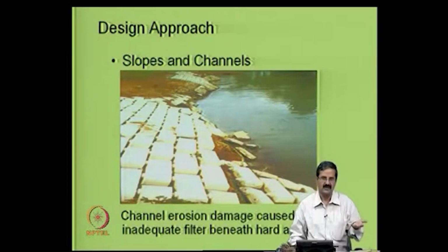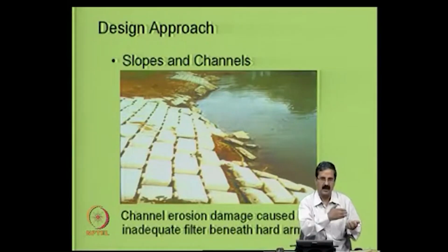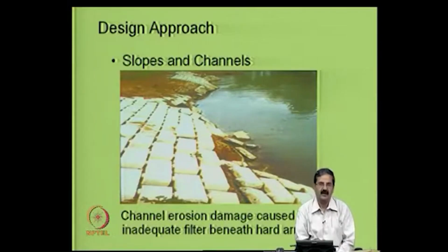The soil is under saturated conditions now, and the effective stress is very low. The water tries to come out, and when it tries to come out, the possibility is that the retaining wall can fail. The bearing capacity of the soil below the small retaining wall is low, so it collapses.